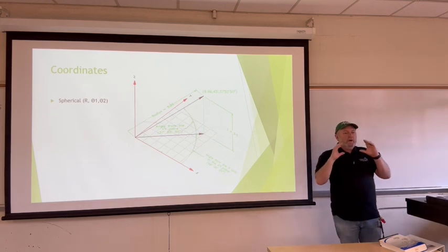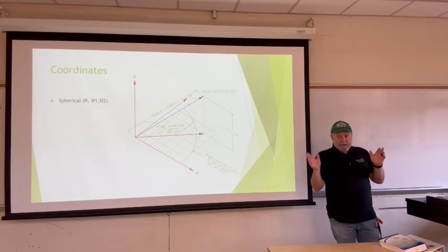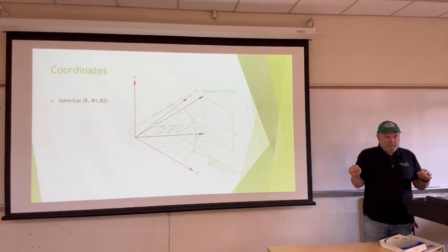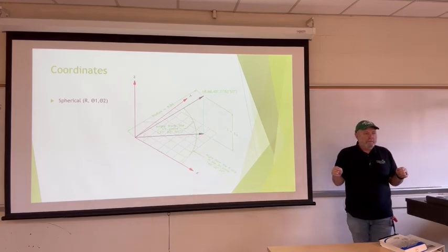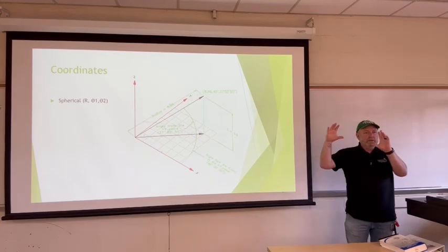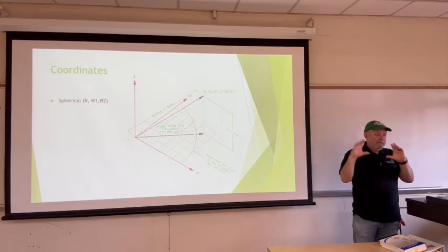What we have, where we're using that ellipsoid right now, from all the math and measurements that have been done, they believe that is about 2.2, 2.4 meters from what they believe to be the actual center of mass of the Earth. We are actually getting ready to modernize our datums where that ellipsoid is going to shift by a couple meters to the actual center.